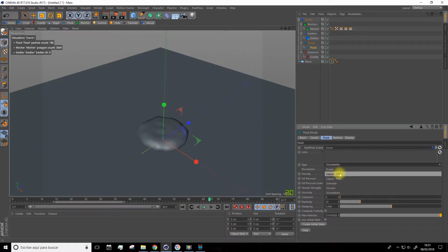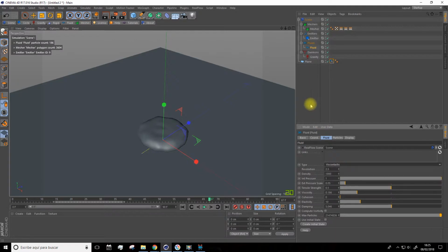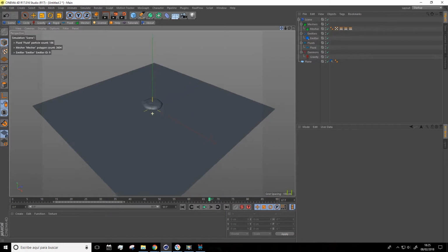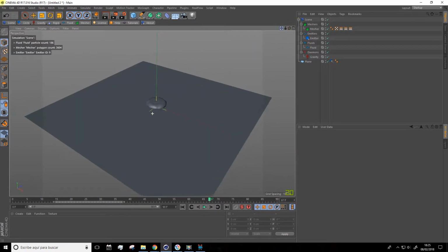So, guys, we have lots of different options. The best part is that we can get quite different results by tweaking the parameters in the fluid panel. Important parameters, as we saw, are the damping, elasticity, and viscosity, which, as their names suggest, work differently and produce different results, okay? So, well, I leave it here. I think I explained to you the main stuff regarding fluids.